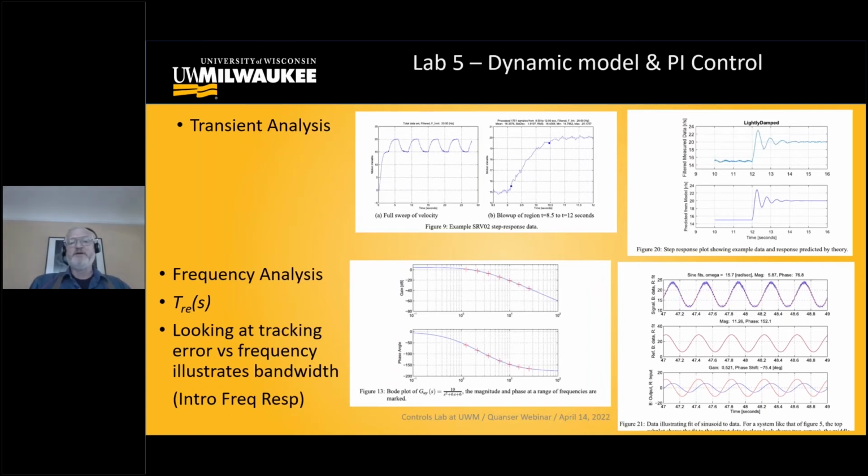And for the first time, we're introducing a model of the plant with a pole in it. The students in this lab develop a first order model looking at transient response. Here you see transient to a square wave voltage input. So we have a first velocity and a second velocity and transients between them. We have some MATLAB fitting tools, so students don't need to develop an expertise in the nonlinear fitting problem of estimating rise time constant in a least squared sense.